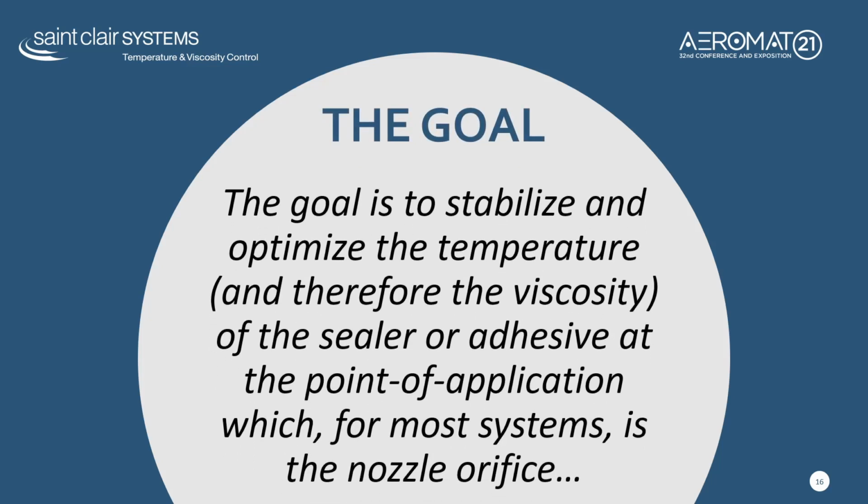The goal, then, is to stabilize and optimize the temperature and therefore the viscosity of the sealer or adhesive at the point of application, which for most systems is the nozzle orifice. With very few exceptions, no other material temperature in the system matters to the stability of the application process.